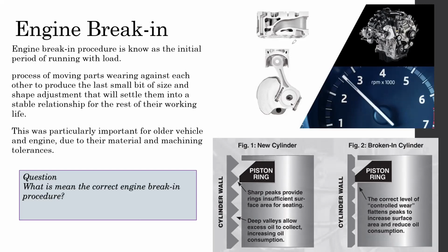If you remember, when you buy a brand new vehicle, they say you have to drive around 1,000 kilometers, less than this much RPM at all times, and after that bring the vehicle to us and we will be servicing it. That's why the first one or two services are free, something like that. So one of the reasons for giving the first service free is that it is part of this breaking-in procedure.